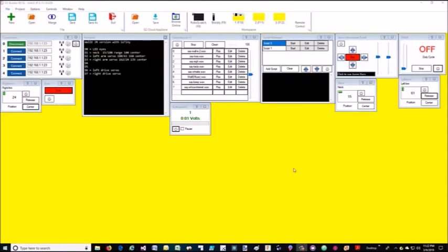To explain how I set up the ADC with the two buttons on WallE, I have a button on the front and a button on the back, and they're both connected to the same ADC line on the ioTiny. So if I press the button in the back, I get one reading, and if I press the button in the front, I get a different reading.